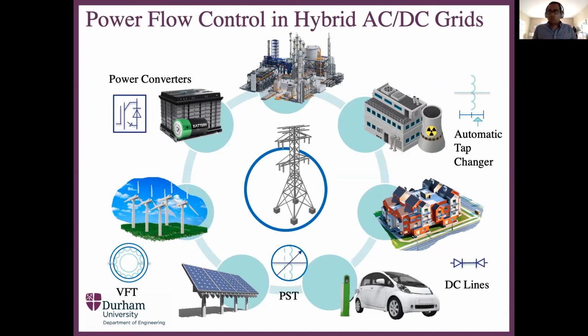For example, you can use two sets of voltage source converters with a cable and create what we call a DC line, or more technically speaking, an HVDC, a high voltage DC line. We use these high voltage DC lines as interconnectors. For example, when you have offshore wind turbines, you connect them using HVDC. Or if you basically want to connect different areas, AC systems together, you can use HVDC. And the good thing about HVDC is that you are able to, again, control power output.